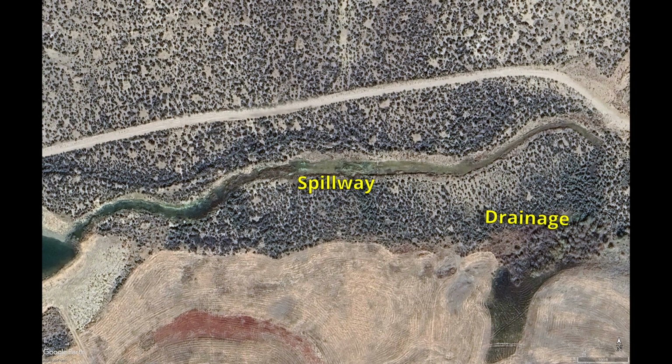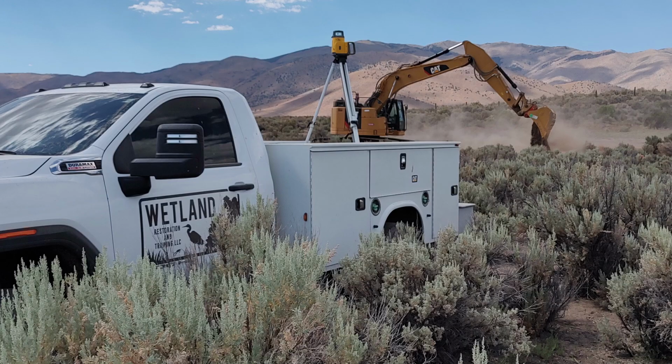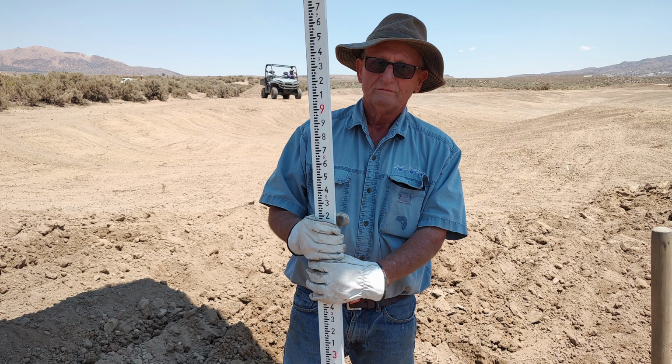without causing erosion. To identify a path for the spillway, we used a laser level to take elevations in the area between the entrance of the spillway and the eastern edge of the property where the drainage was located. Because of the thick and tall plants, we set up a tripod and a laser level in the back of a truck so it would be high enough to clear the vegetation. We used the laser level to record elevations so we could mark a path for the spillway that changed only 6 inches from the entrance to the exit of the spillway.